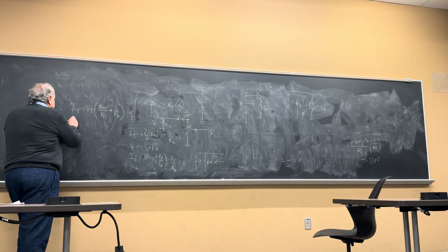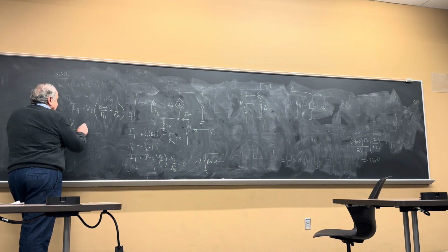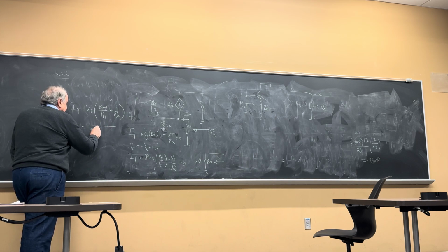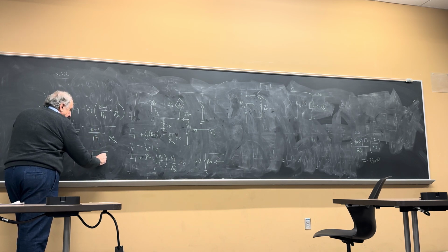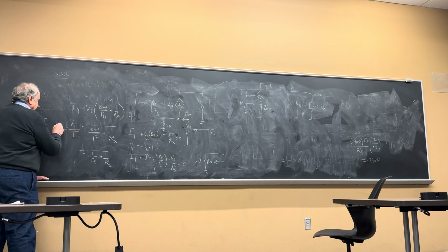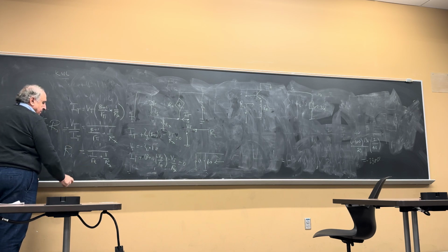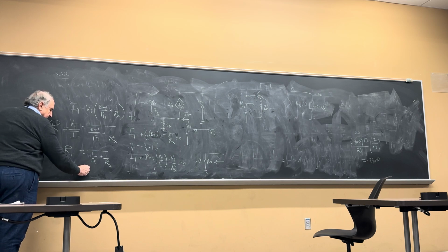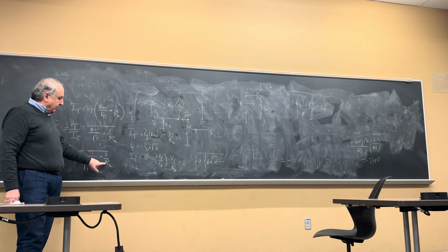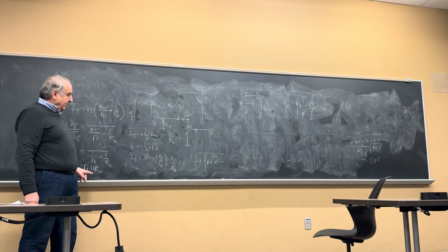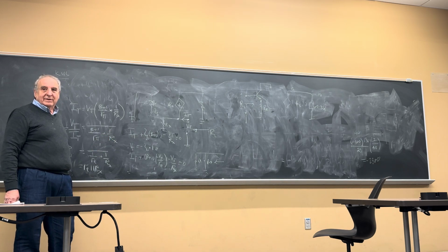Okay? Now I'm looking for the impedance. What's R pi over beta plus 1? This is Re. Rx plus Re over Rx Re, flip it around and they become in parallel, which is what Taylor got, very simple with the T model. But the pi model gets you there.